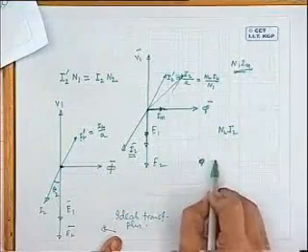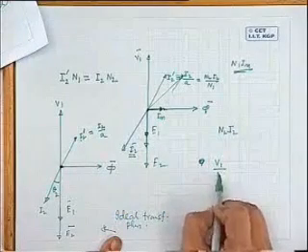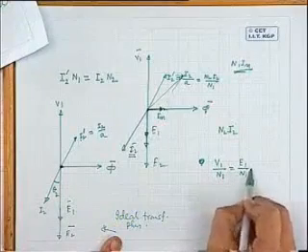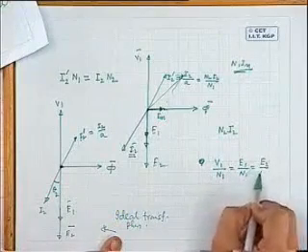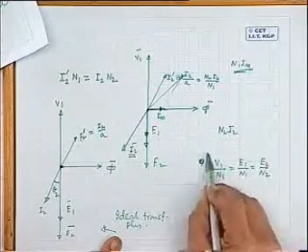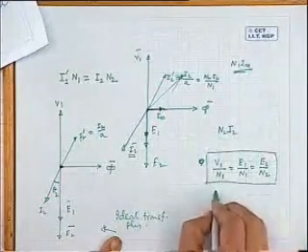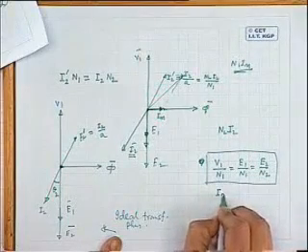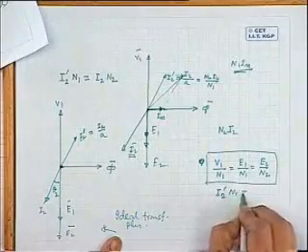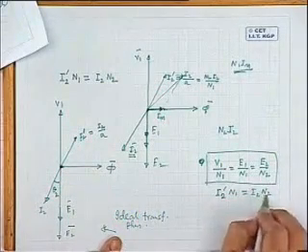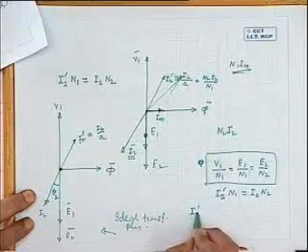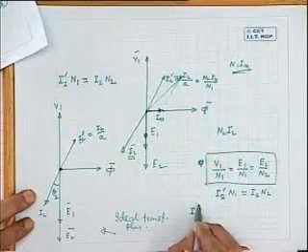So this relation, apart from the voltage relation that we got in our earlier class, that is the voltage per turn remains constant, V1 by N1, or rather E1 by N1 is equal to E2 by N2. This was the voltage equation we got. Now we get another important relationship, that is, I2 dashed into N1 is equal to I2 N2. What is I2? I2 is the actual secondary current. What is I2 dashed?